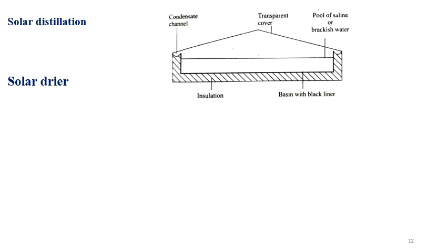The operating efficiency is about 35 to 50% for the basin type still, compared with the theoretical maximum of slightly more than 60%. The performance rating and efficiency of the solar still is determined by plotting a graph of the amount of fresh water produced per unit of basin area in one day versus the solar radiation intensity over the same period.